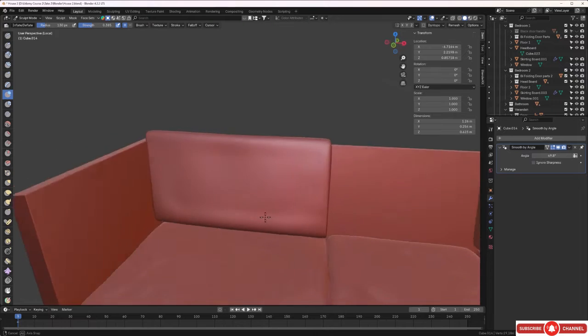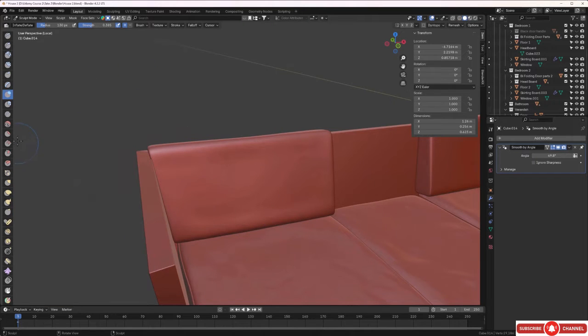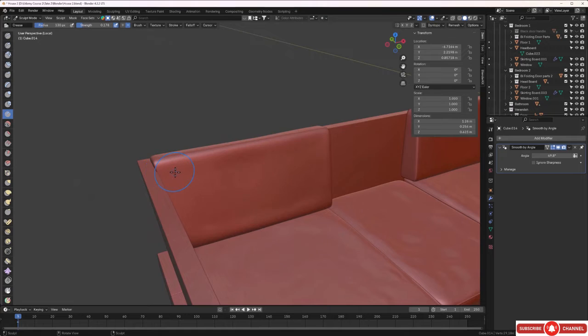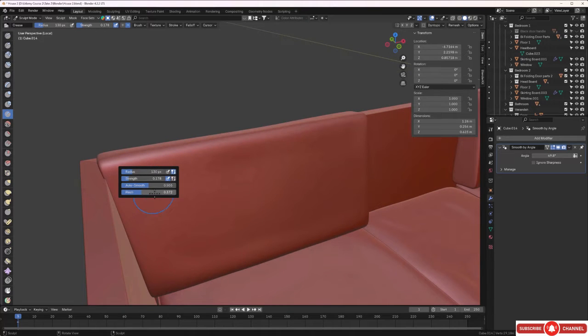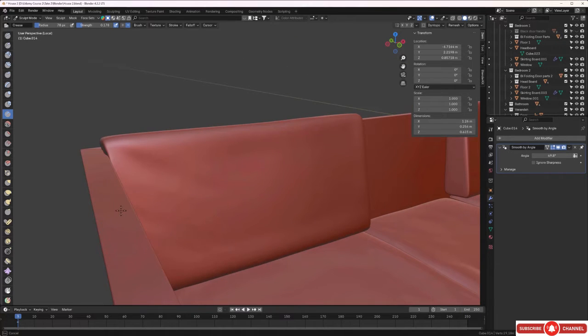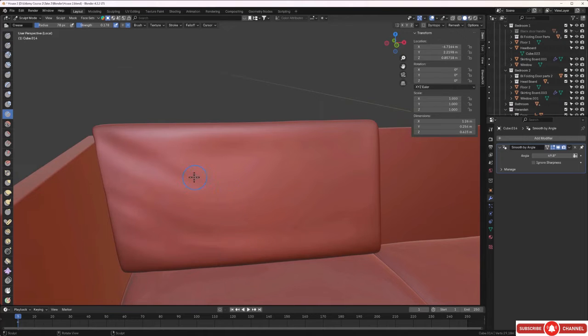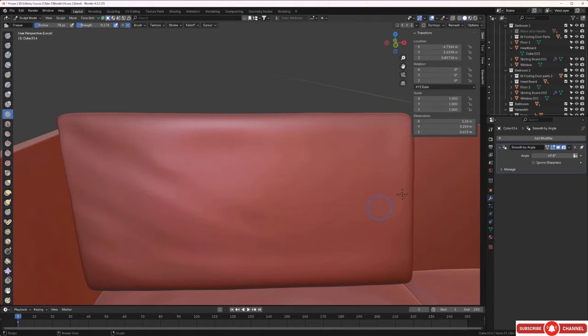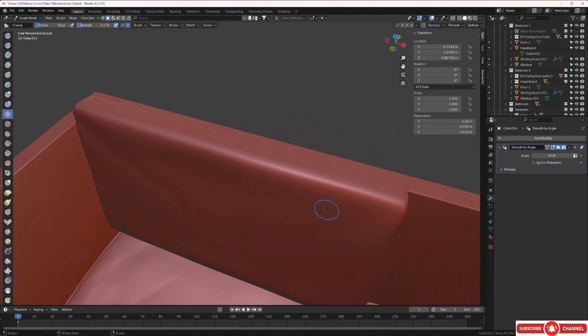There we go. So I'll use the crease brush now, grab this one, and let's right click and see where we're at with it. And let's just see how this goes. So I'm going to grab one and maybe put it in here like this. I'm going to reduce the radius, it's too much. Try that again now. And put one in here. And put one in here. And I'll continue this one, I think, across the sofa. And put one in here like this. And maybe here. And I'll reduce the radius some more. And now we put one across here like this.